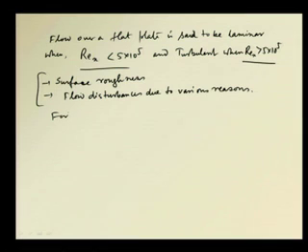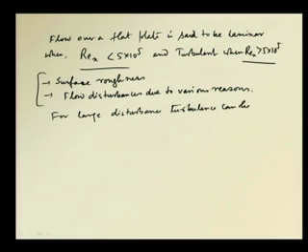For large disturbances, turbulence can happen at Rex nearly equal to 10 to the power 5. Forget about 5 into 10 to the power 5, it could be 1 into 10 to the power 5. So, that is what I was trying to say, that it is not very hard and fast, it is subject to certain discretions, subject to certain decisions.